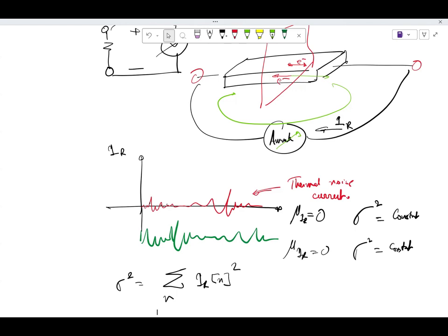So naturally, it doesn't make sense for us to observe these things in time domain. I have to observe it in another domain where the statistics is a part of the math, right? Because in time domain, I cannot do anything. So hence, noise analysis is almost always done in a statistical domain. Okay, so you always talk about mean, variance, and you talk about various domains so that you want to come to mean and variance.